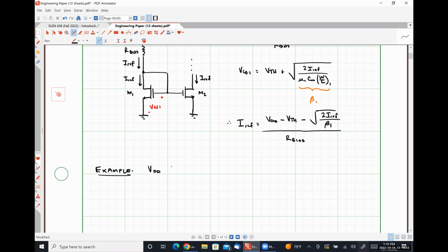So this is a VDD equal to 5 volts technology node. These aren't the exact values for the C5 process, but they're pretty close. For NMOS transistors, we have a minimum aspect ratio of 10 to 2, and the same exact value for PMOS.